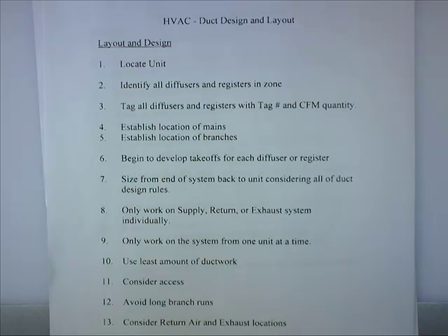Seventh step is where we would begin today. Size from end of system back to unit, considering all of duct design rules. So the last thing that we talked about last time we did a preliminary ductwork layout, we talked about getting all the CFM quantities for each section of ductwork. So you should have those at this point.